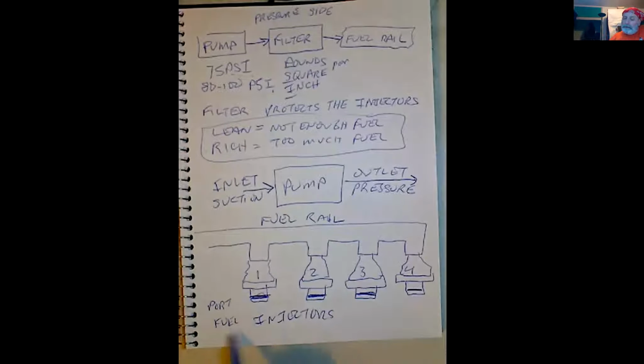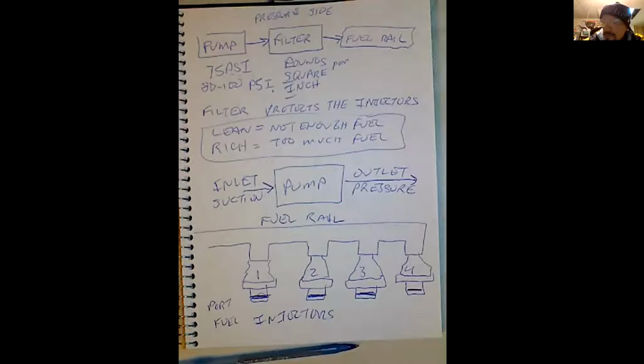So the port fuel injectors are going to spray fuel right on the back of the intake valve. During what stroke? Intake stroke. Piston's coming down, intake valve is open, it's sucking a bunch of air in, and we're going to squirt a bunch of fuel in with the air.